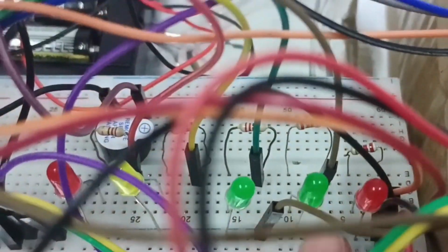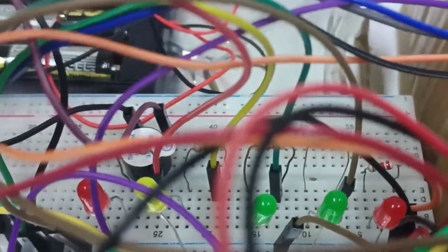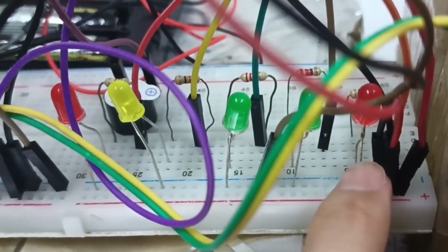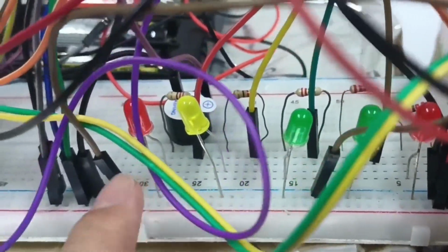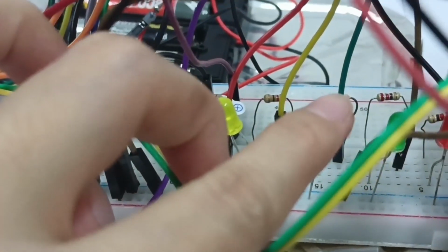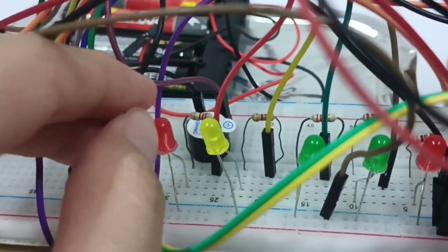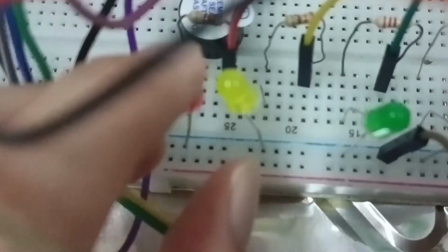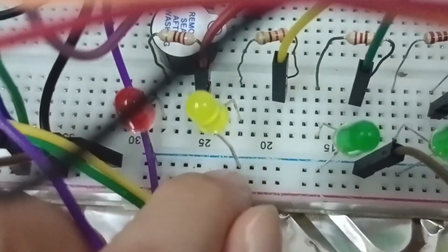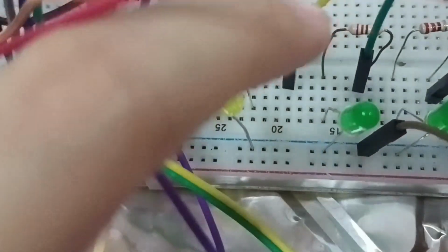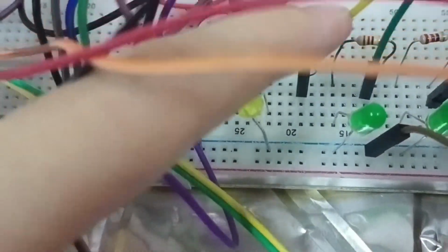These two are the smoke detection LEDs, the green LED connected to the PA6 and the red LED to PB9. And these 3 are the temperature detection LEDs. The green connects to the PA9, yellow to PA8, and red to the PA7. Each cathode of the LED is connected to the ground, while the anode passes through a resistor before connecting to the output pins at the Blackpill.